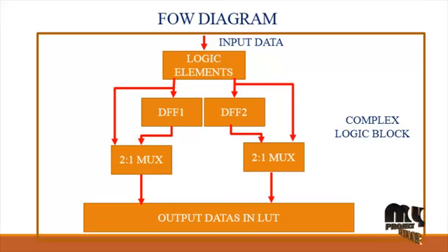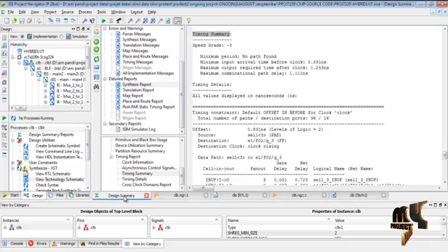Next one, the lookup table. A LUT, which stands for lookup table, in general terms is basically a table that determines what the output is for any given input. In the context of combinational logic, it is the truth table. This truth table effectively defines how your combinational logic behaves. In other words, whatever behavior you get by interconnecting any number of gates.